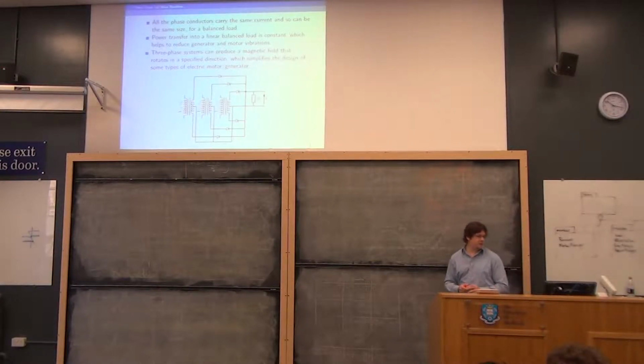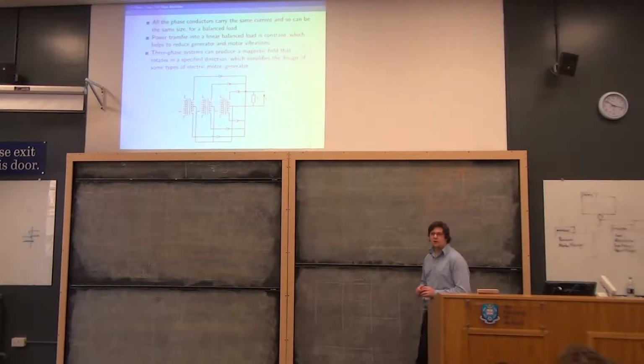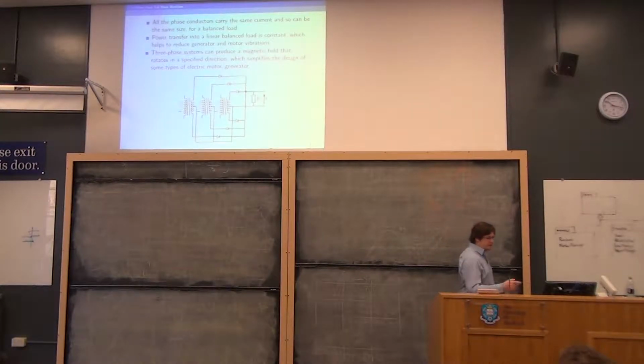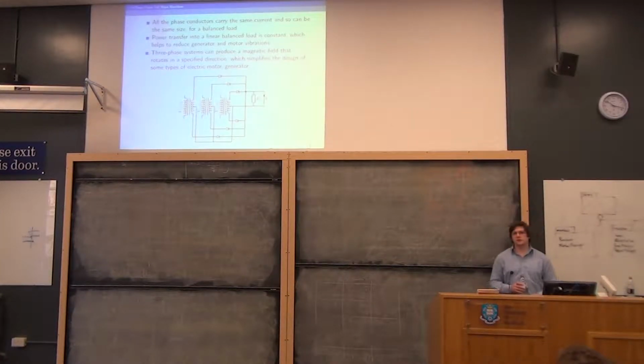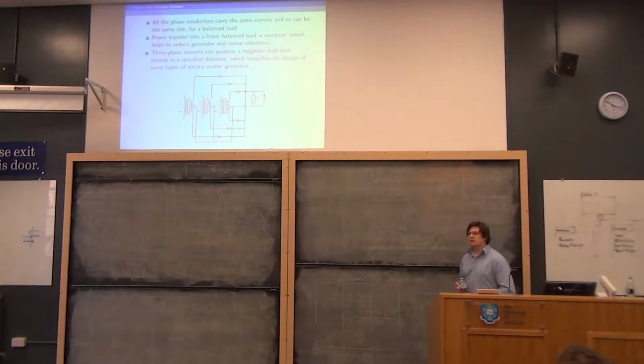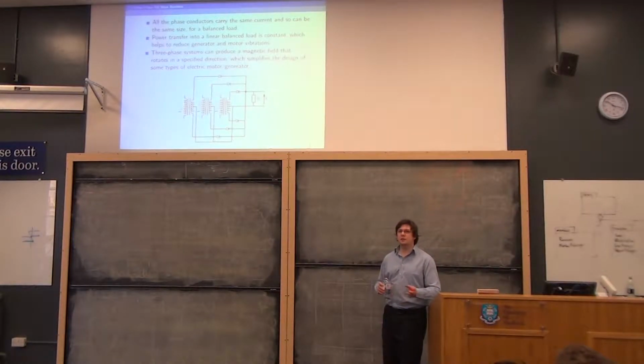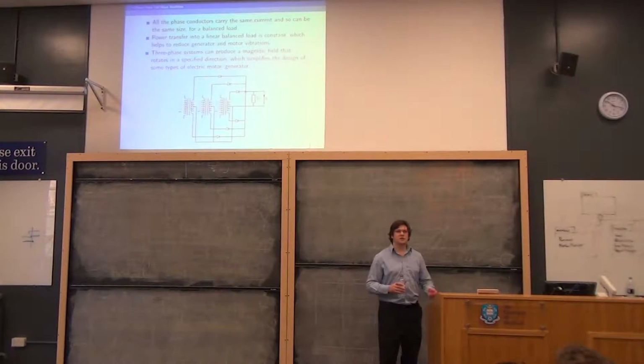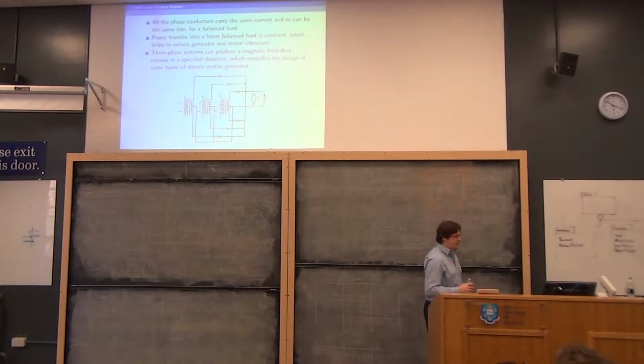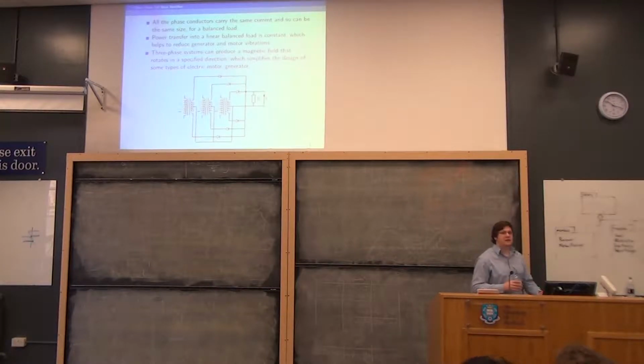So that's to say, if you were to drive a resistor off all three phases, as I have in that diagram there. So this is three phases and three full-wave rectifiers composed of two diodes each. So this is the simplest of the full-wave rectifiers, and it's just copy-pasted 3 times. And I've said they're 3 different phases, but unless I'd said that, it isn't necessarily true.